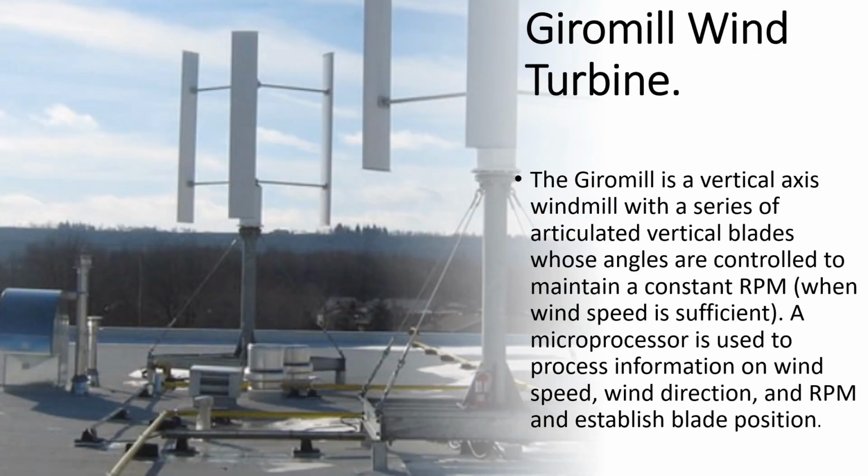The gyromill is a vertical axis windmill with a series of articulated vertical blades whose angles are controlled to maintain a constant RPM when wind speed is sufficient. A microprocessor is used to process information on wind speed, wind direction, and RPM and establish blade position.